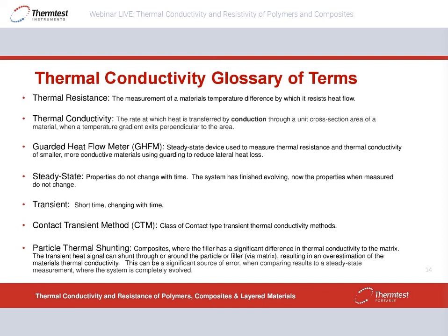the ability to schedule pressure, temperature, and/or thickness change. So you could actually set up an experiment to mimic an application of a thermal interface material between a chip lid and a heat sink or something like this. That's a pretty important advancement we've made in this method, to be able to do that all automatically within one schedule.